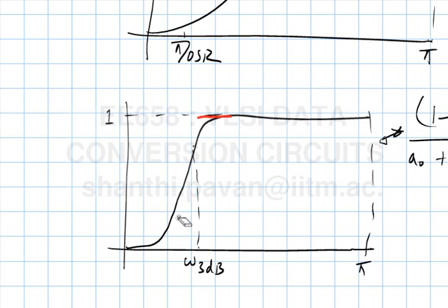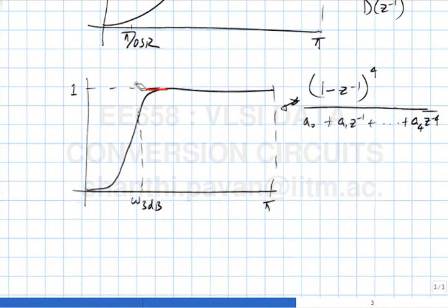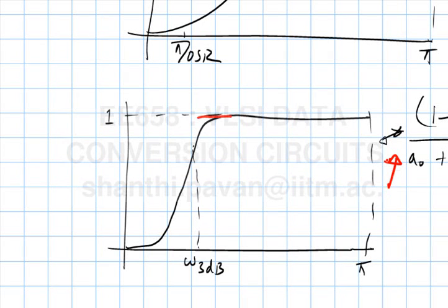But the bottom line is that it is possible, using MATLAB or any other numerical evaluation tool, to figure out the transfer function of an nth order high pass filter with all zeros at the origin, or in the z domain, all the zeros at z equal to 1. And then we realize that, hey, why bother trying to figure out pole positions? We might as well start off with a Butterworth characteristic. If you start off with the Butterworth characteristic, so this is a fourth order high pass filter. Can this be a noise transfer function?